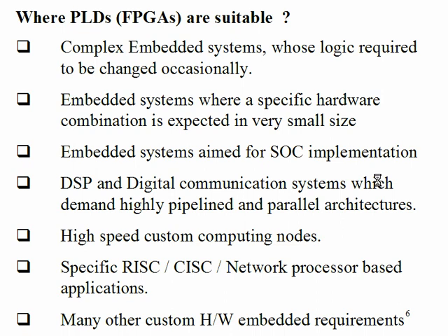Then I can use FPGA. 4 processors, whatever you want, use 4 RISC processors in it. Whatever decoding logic you want, you write the VHDL code and put it on top of the FPGA. Use logic cells to configure as a decoder. You write the VHDL code or Verilog code or C code for the CAN interface, put that also on the FPGA. Now you see, anything you can write the VHDL code for it and put on the FPGA. So I am getting all the variety of peripherals in a single chip, which comes in this much size. You got the point or not?